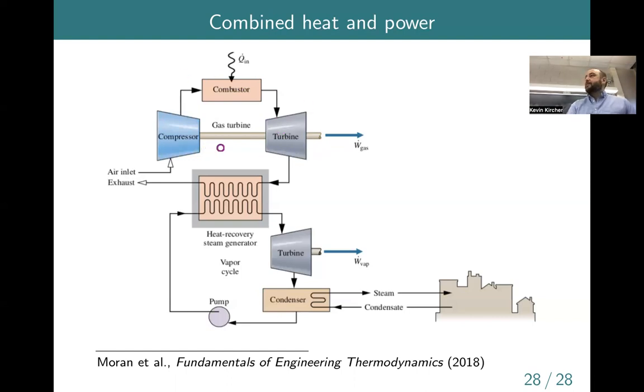That would be just a simple gas cycle by itself. You'd stop there and say, okay, you're getting work out, you're putting fuel in. But now we have all this hot, fairly high pressure gas coming out of the turbine. So you can do something with all that heat: run it through a heat exchanger and use it to warm up water. It would actually boil water down here typically. Then you'd have steam coming into a second turbine, a lower pressure, lower temperature turbine, and that would produce another work output.